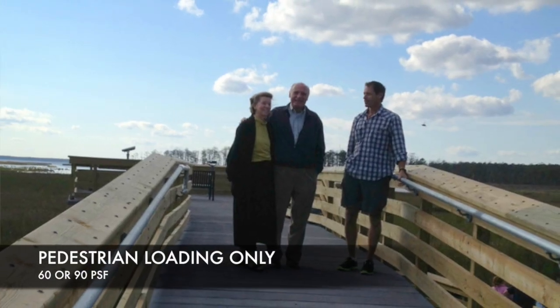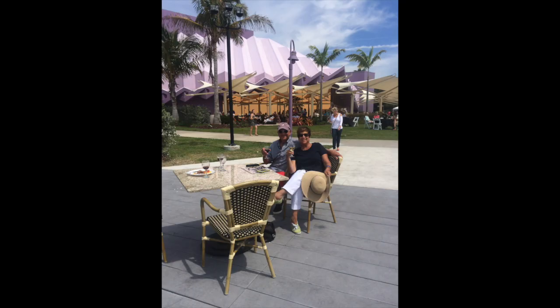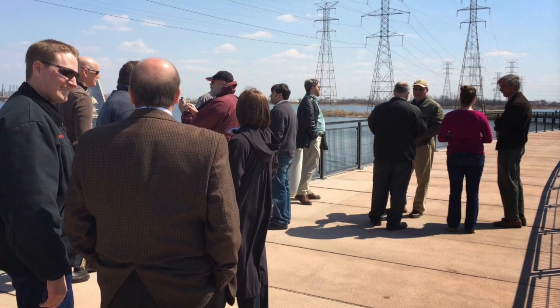required to design for potentially from a vertical standpoint is maybe a pedestrian loading. You may be looking at something like 60 or 90 pounds per square foot. If the walkway is being used as a platform, as an observation pier, then you're going to get more than just a single file traffic. You may have to design for some larger floor loads that it could be 100 or 250 pounds per square foot. Think about these amphitheater areas. You have to look at the context of the boardwalk system itself.